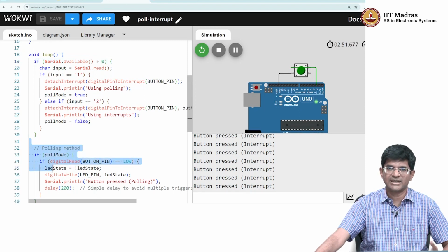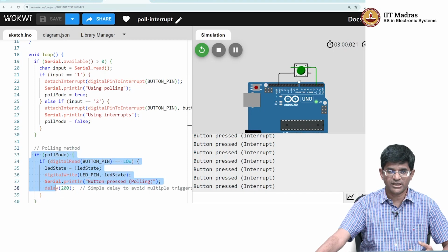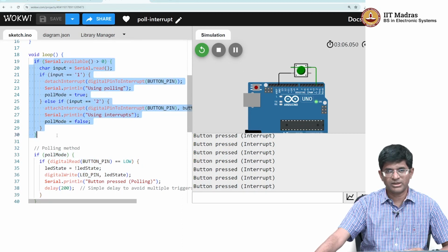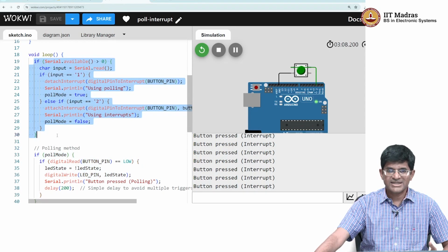And that is typically exactly how polling works. So even though the code was written so that I could demonstrate polling to check the state of the button, purely by coincidence, the very act of allowing me to change between polling and interrupts is made easy because I use polling to find out whether there was data present in the buffer, and if so, to respond to it.